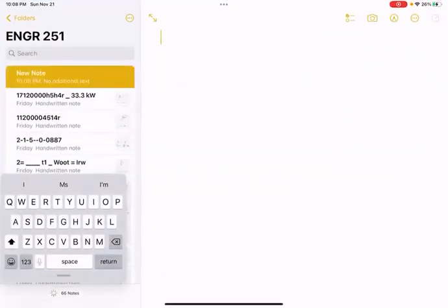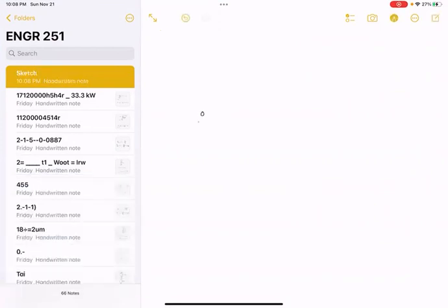So yes, this is a cycle question. So let's just briefly review the Rankine cycle. We have 4 steps. So we start at state 1, and we go through a pump. So what does a pump do? It just adds pressure. It brings your pressure up. So by the time we get to state 2 over here, we're at a higher pressure. Then what happens? Well, we go into a boiler, and the boiler increases our temperature, but does so isobarically. So the pressure from 2 to state 3 stays the same, but the temperature goes up.